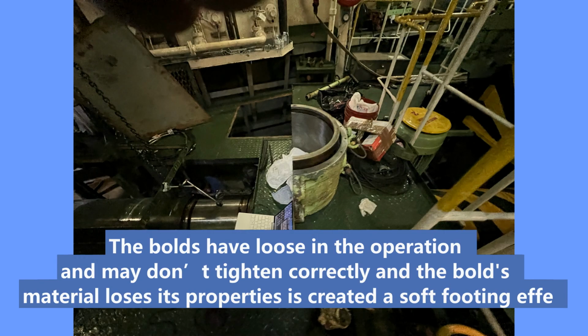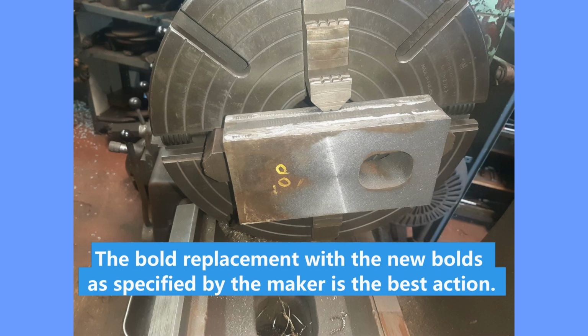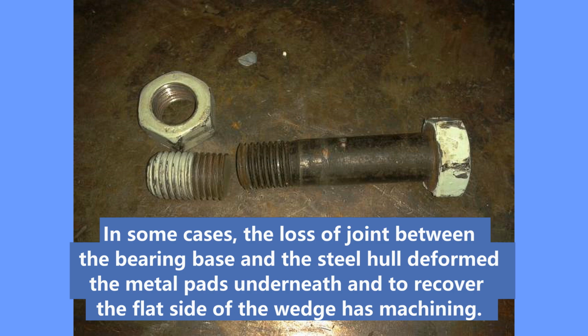In some cases, the loss of joint between the bearing base and the steel hull deformed the metal pads underneath, and to recover, the flat side of the wedge has machining. The bolt replacement with the new bolts as specified by the maker is the best action.